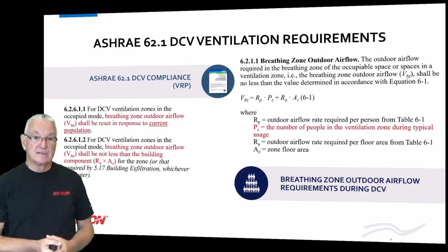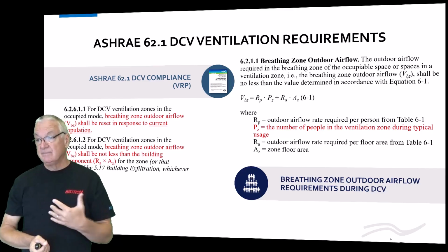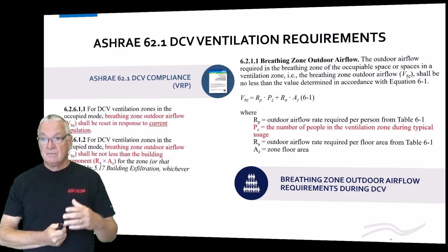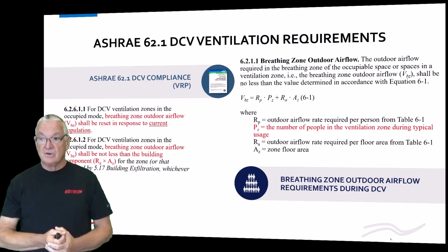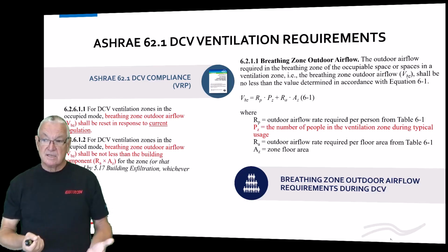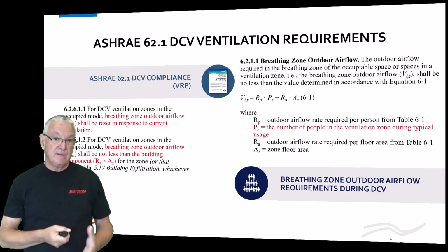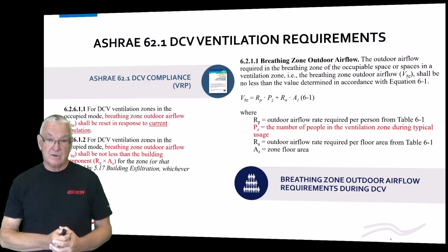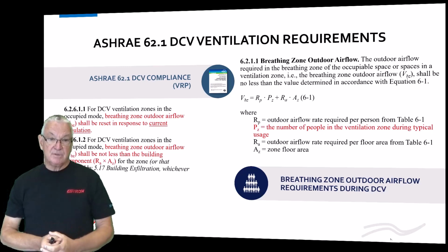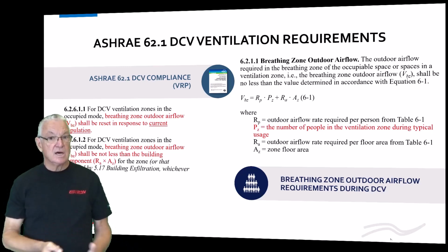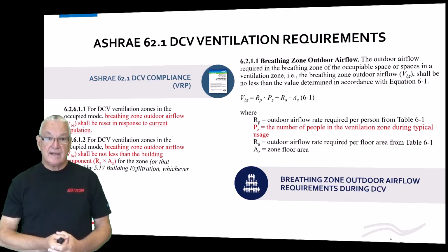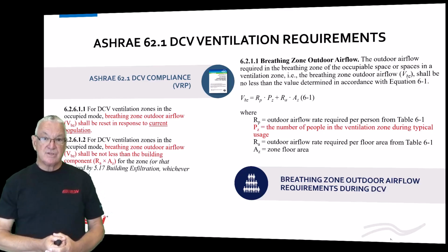It doesn't clearly say that, and I think it allows a lot of people to bring the ventilation rates down below the exhausts, and you run some buildings negative, you create some IAQ problems. I've even seen where people don't pay attention to this floor component, and they just shut the outside air completely off. Well, you might have local exhausts, and you're creating a negative pressure situation, which isn't great.